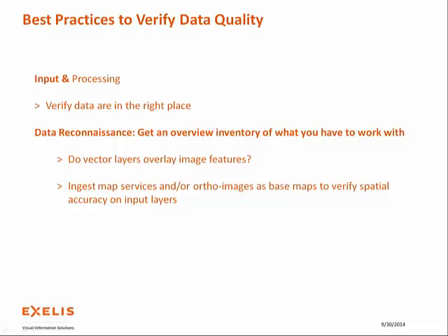Data resolution also plays a role here, where 30-meter pixel data offset by a meter is a lot different than a 30-centimeter pixel off by the same meter. So accuracy is going to have a large effect on the end result. Additionally, most analyses these days incorporate more than one layer.